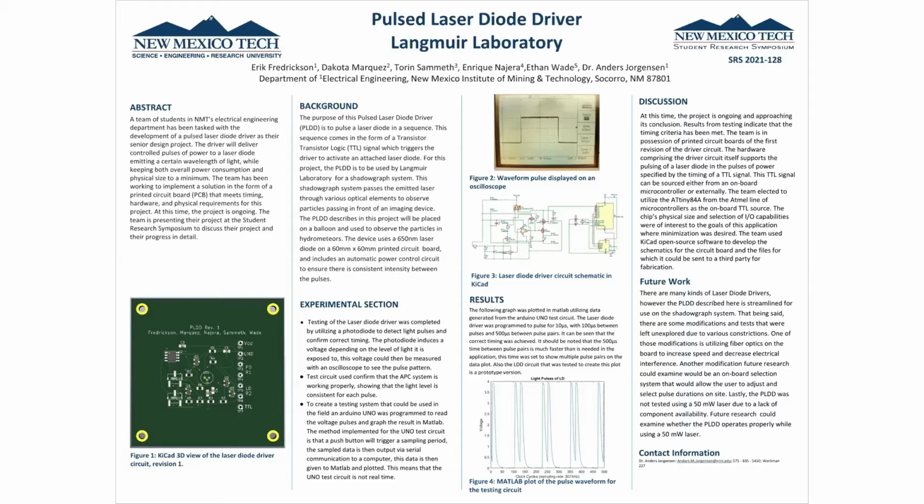That exact graph is from a prototype board, since we just completed the PCB yesterday. And so that's just to confirm that this testing system can be used to confirm timing and confirm that the light is producing the same level of light for each pulse.